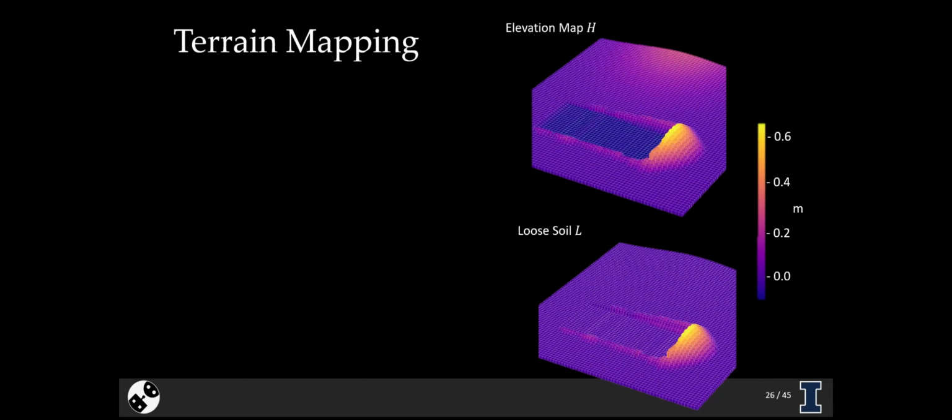But additionally, we're tracking this loose soil layer. By assuming the initial terrain is compact, then for all of the movements that we make within that soil, we can say that when it's displaced, it becomes loosened, which is important for us to estimate the surcharge volumes, the amount of material that's built up on the front of the blade, which is an important input to the FEE equations.